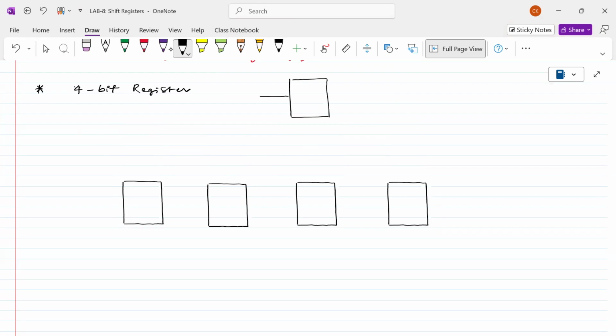We have 4 data inputs, let me call this D. We will have a 4-bit output, which I call Q. This data will be stored here or be transparent based on the clock signal. But before the clock signal, we have to give the reset signal as well. First of all, we have to clear the content of all the flip-flops, then we apply the clock signal.